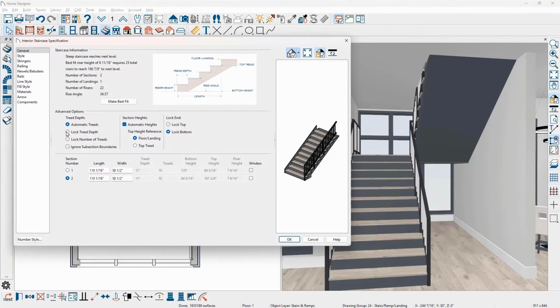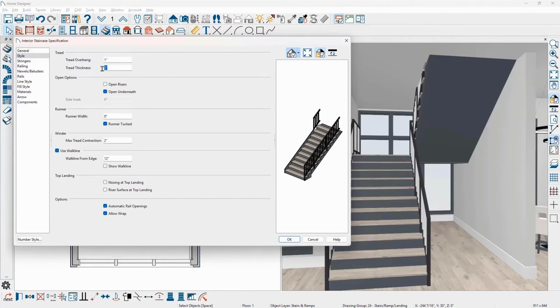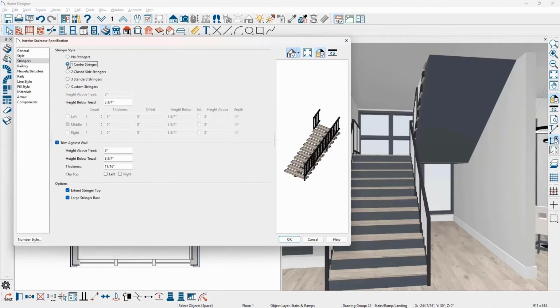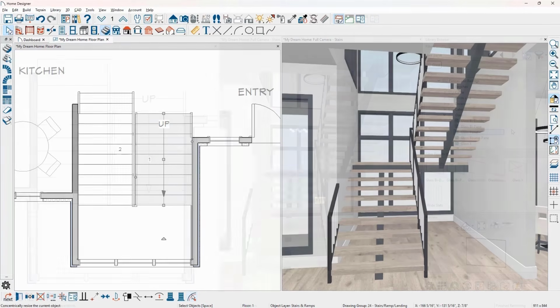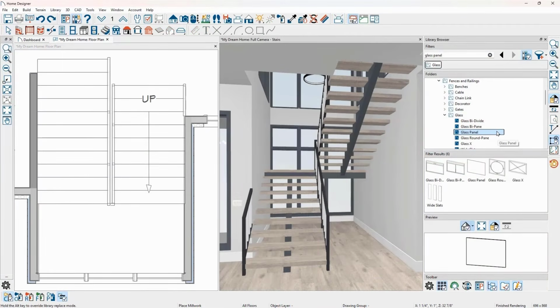To modify these stairs, I'll begin by changing the number of treads for a mixed symmetry, including the tread thickness, with open risers and a center stringer. Using the Auto Stairwell tool, create the opening on the floor above and then move up to floor 2.